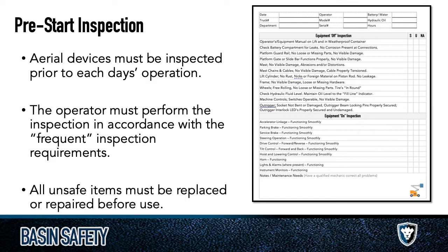And the other thing, for both forklifts and aerial lifts as well, super important, and a lot of people skip this on the inspection, is air pressure in the tires. Especially if they're inflatable tires; some of them are solid, so it's not an issue. But if you have an inflatable tire and one of them is flat, I promise you, it's going to affect how safe you feel in that equipment. It's going to affect how much you can load it, how quickly and easily it moves, how bouncy the ride is. Make sure your tires are full.